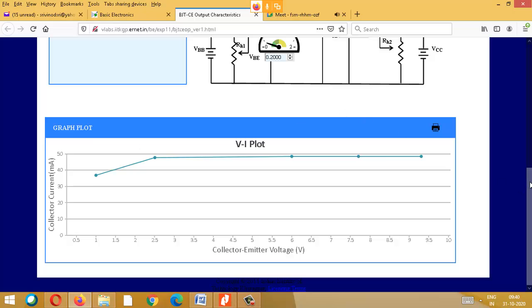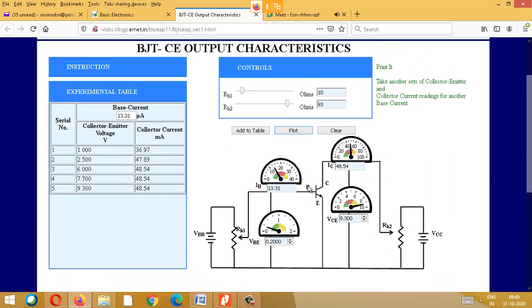So when I am increasing my input side, what happens? If I am increasing the base current, the flow between these will be there. So that is why this is called an active device. See, the base plays the major role. I repeat, the base plays the major role with respect to output characteristics. When you want more current to flow across your collector to emitter, or in any application when you want to control your output current, this output current can be controlled only with the help of base current.